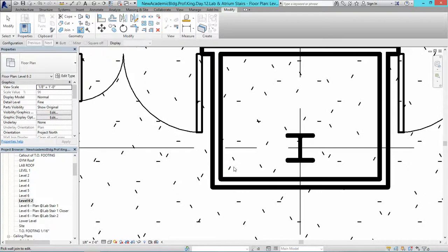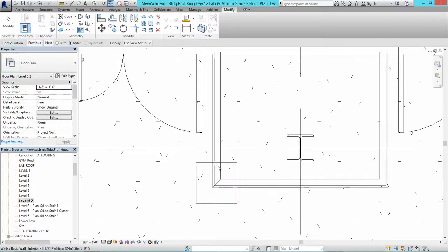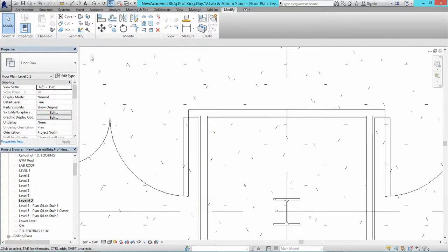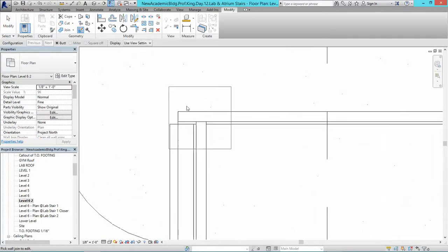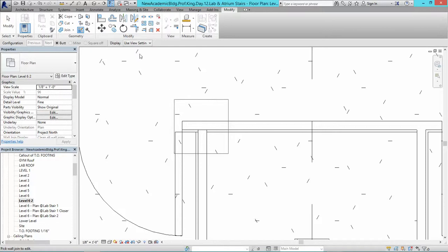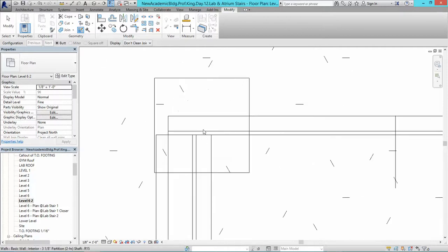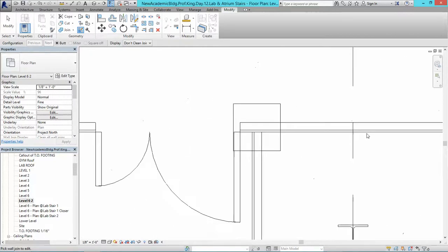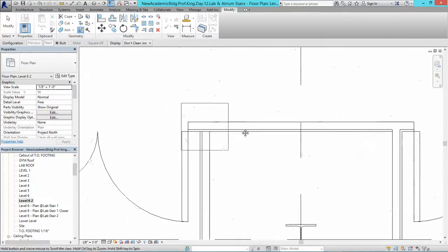So that's great. Once we have that, you also have the option of pressing join and selecting that element. When you have a T connection between partition walls, you only are able to change the display. But this is a good chance to see how you can make the sheetrock go through it and make the partition wall meeting that previously mentioned one stop a little bit earlier from that sheetrock element.